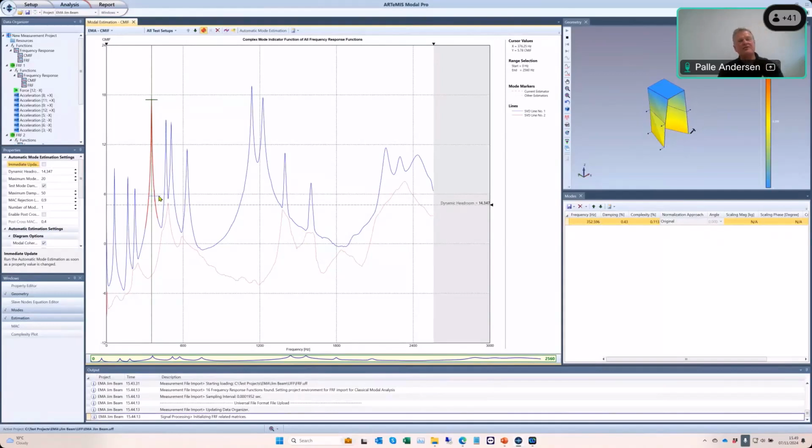This allows us to get an improved estimate of the mode shape, because we now have many mode shape values we can average together. It also gives us the opportunity to estimate the natural frequency and the damping. We do that in frequency domain with a simple least squares estimation.